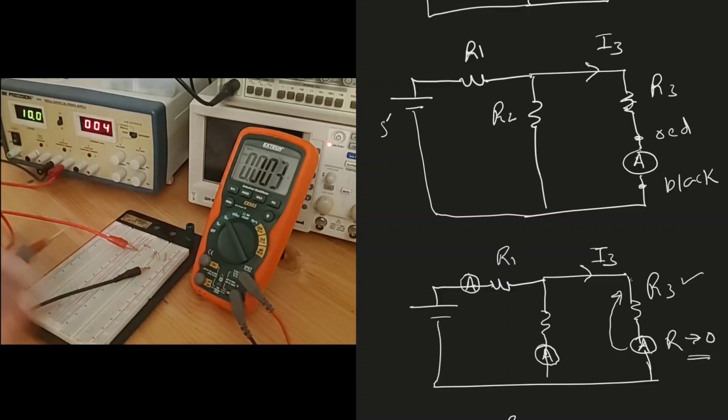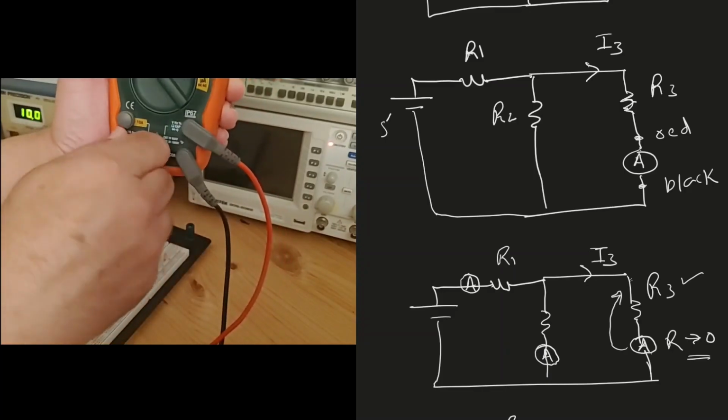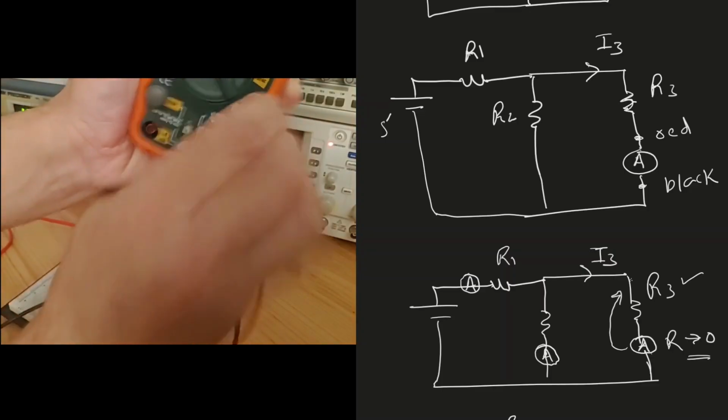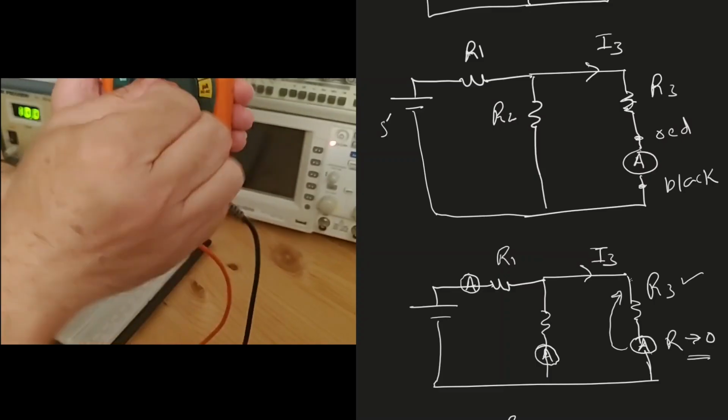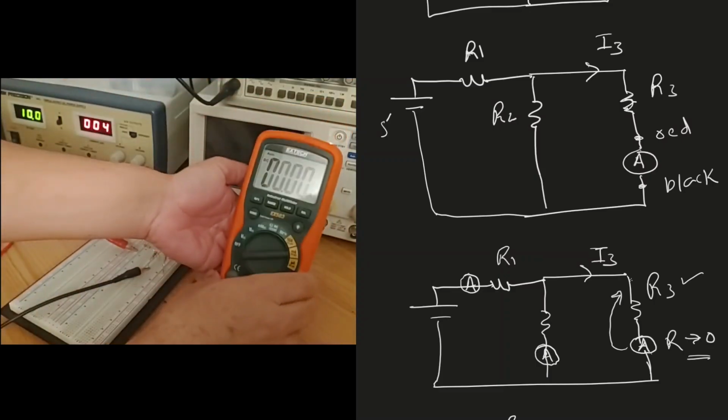That's okay. Now, to measure the current, because my current is small, I will use the milliampere. So let's take the probe off from here and connect it over here. And now we will go to milliampere. Over here we have milliampere.